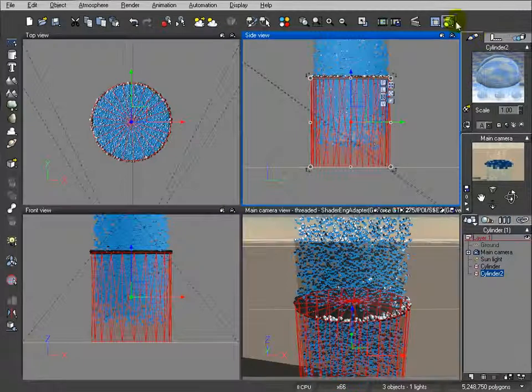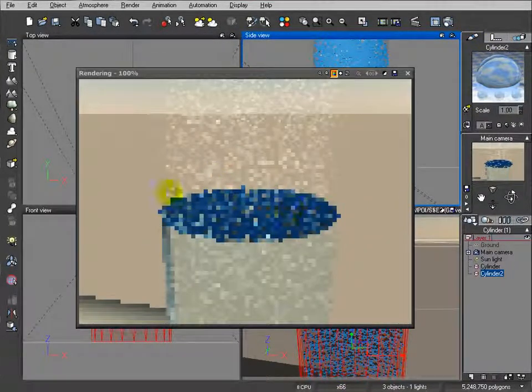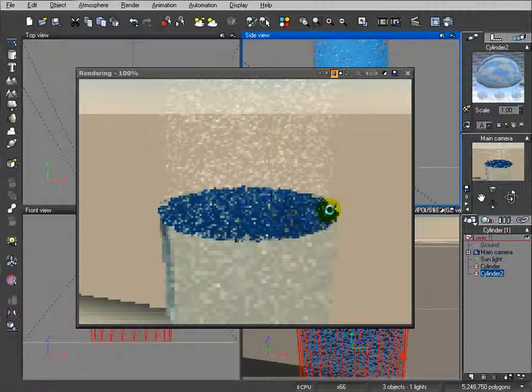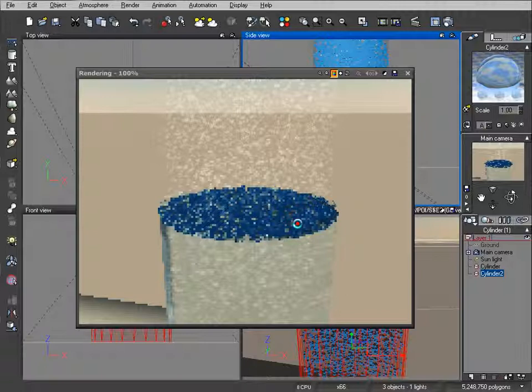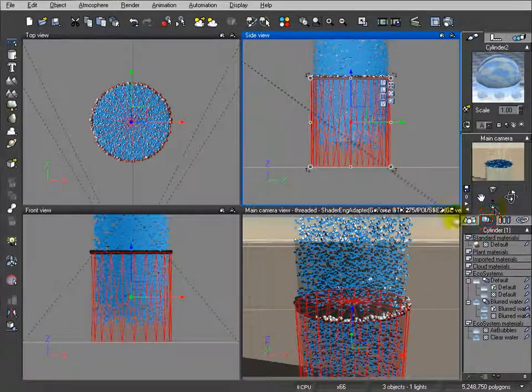Okay, if we preview at this point, you will notice they have different colors. Sometimes when you work with materials and apply them to an ecosystem, you want to modify the material without overriding your object. So we can go inside the material tab, and right here you notice we now have ecosystem materials, and we have a different name, so we can go ahead and modify.